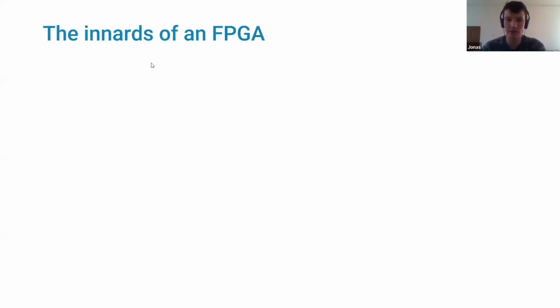I would like to keep going on the NTT because I think there's a lot of things that can be improved. You can make NTTs a lot faster on FPGAs. FPGAs also have nice features for integer arithmetic, they are very much built for integer arithmetic. There are some really nice things, but without giving too much away, for example, you have adder elements on the FPGA itself that work very well for splitting up your additions over one specific slice.